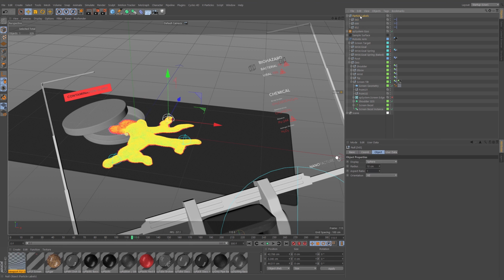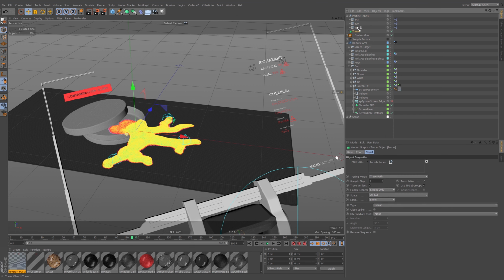Excellent. And let's add a tracer object. Let's grab our first tracer object, and then we'll probably be duplicating after that. So go to MoGraph, tracer, make it a child there. The first one we'll do is we'll connect up these first 2 points. Point 1, oh, because I had an object already selected, it threw it into the trace link.